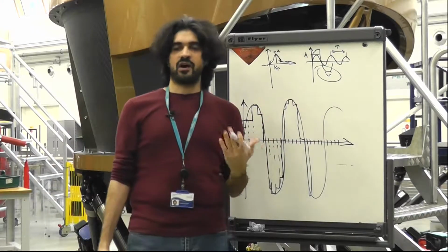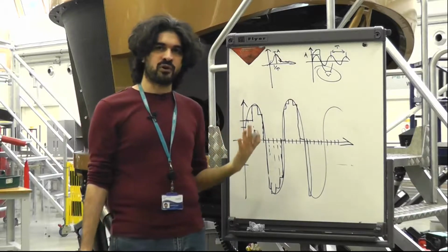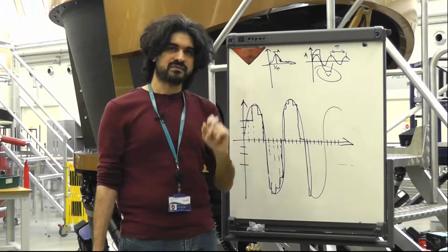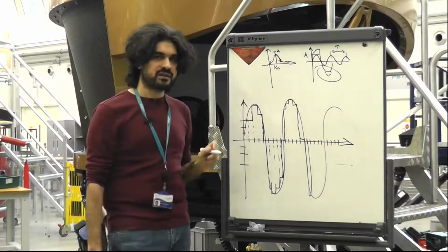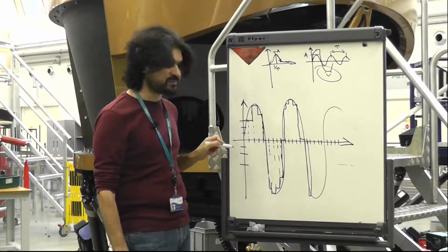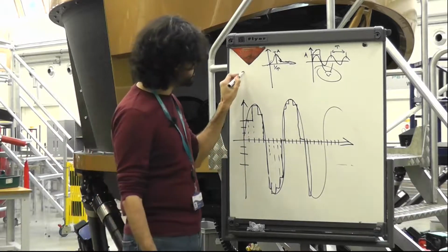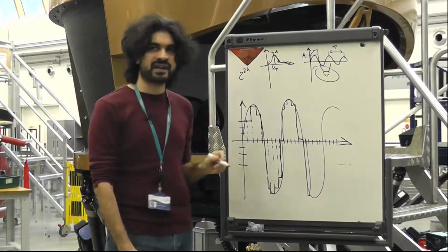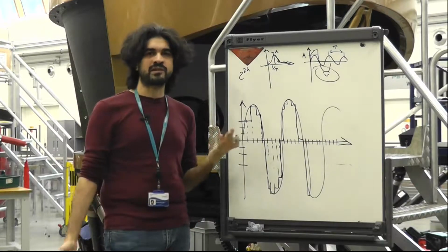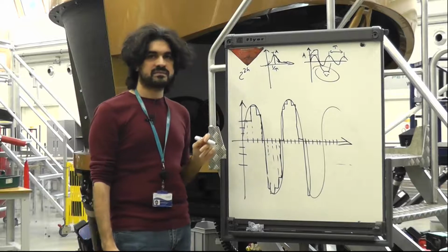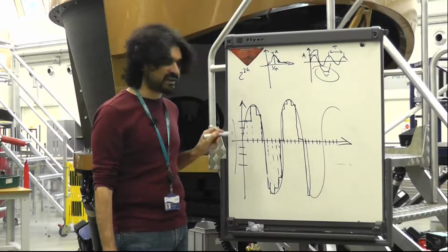But again, on the other end, you also want to avoid being too small, because what happens if you have a range that is too small? That means out of the 2 to the power of 24 levels, you might only be using 3 levels, or in this case 7 levels.